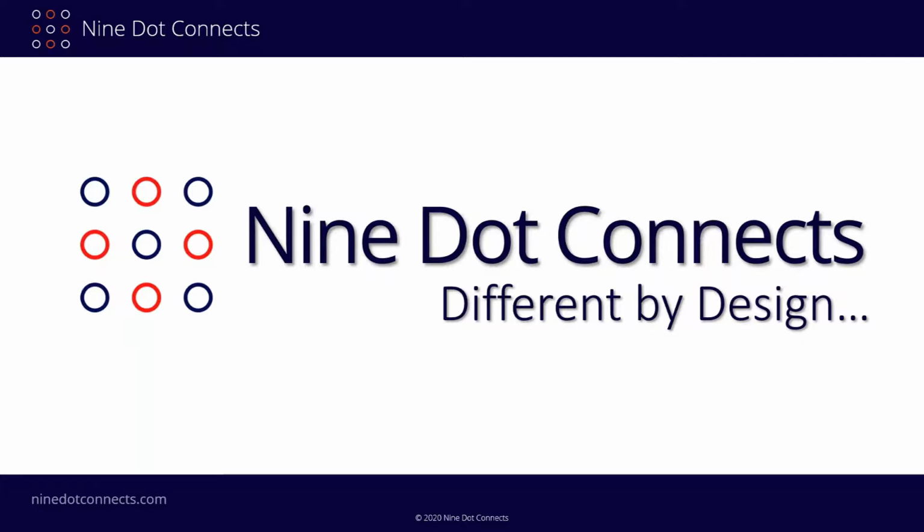So for example, let's take the resistor, because I think you hit on all the key points of the resistor. If I was going to have a description for a resistor, it would start off with RES, just so that I can sort it based on component type. Then it would be the resistance, and again, I'd be very careful about how I did it for sort purposes. Then something like the tolerance, the wattage, and then the packaging, the case size. That's normally how I do that. And pardon me, there's also the ppm in there as well.